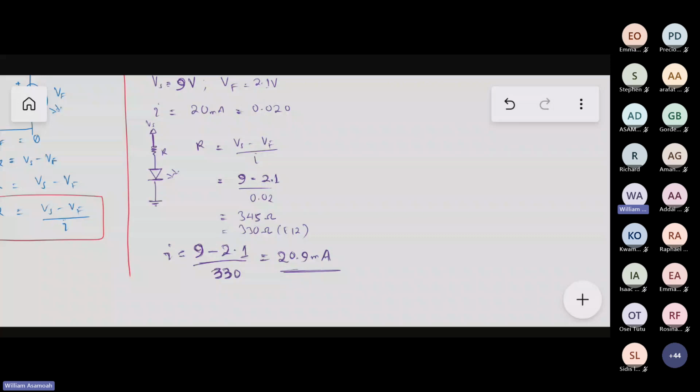So if this thing is working, and then environmental influences come upon it, it still works reliably. But the Chinese, because they want to cut down cost, if the resistor is a quarter watt rating, and the power rating you calculate for the resistor is 0.25 or 0.24, they go for the quarter watt rating. A quarter watt rating can take 0.25. Yes, because it will make the device cheap.